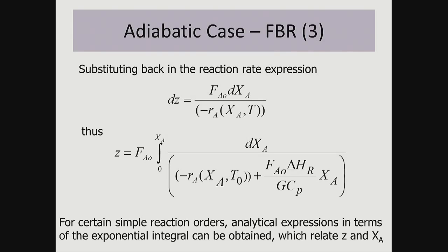Basically, all I've done is I've done an endothermic reaction where the temperature drops, and I've got incremental conversion down the bed, and I've calculated it just numerically. So it's a numerical integration down the bed, because what is integration? It's just incremental step changes. So look at what the equation is.